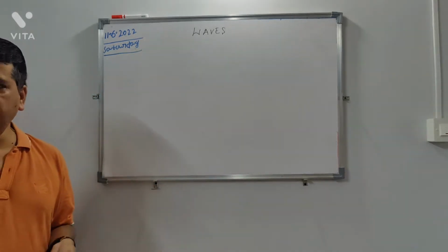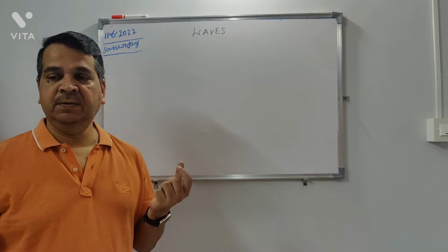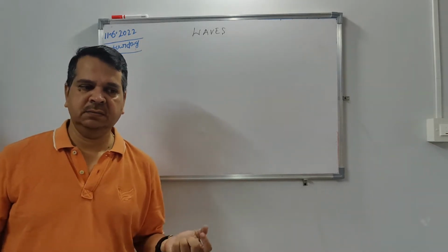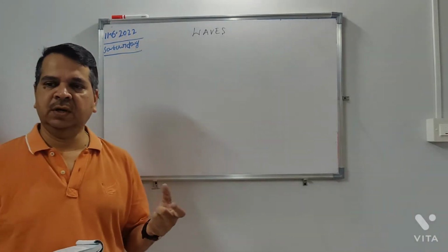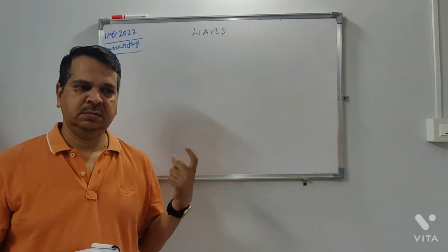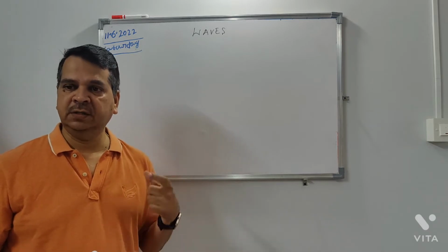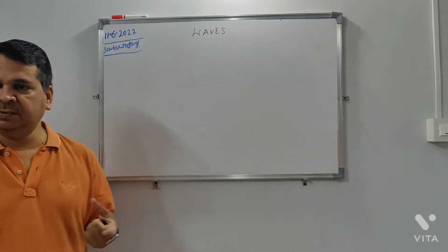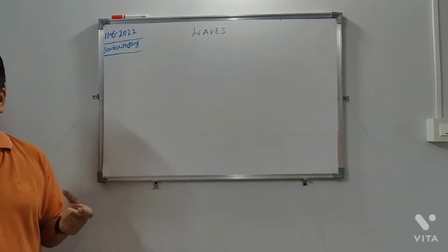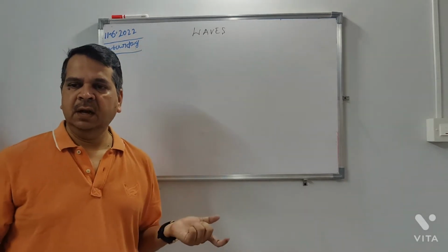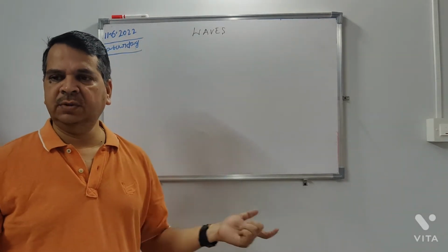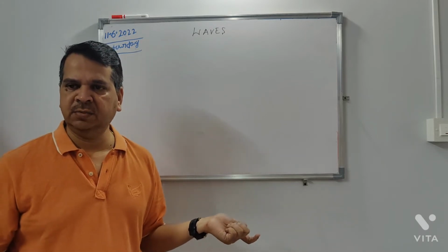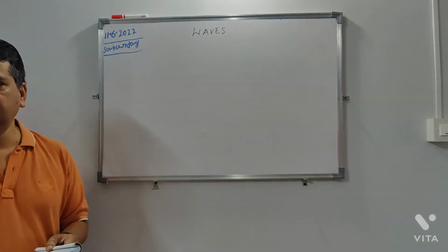As compared to the kinematics, here if you develop the understanding, you can easily do the numericals. It is statics, it is easy to do, but as compared to the kinematics, it may be a little tricky and it may take a little longer. But in thermals, if you understand how the formulas are derived, the formulas are not complicated. Like the Carnot engine. If you know the concept, the efficiency is equal to 1 minus T2 by T1. T2 is the sink temperature, T1 is the source temperature. That's all, you can find the efficiency.